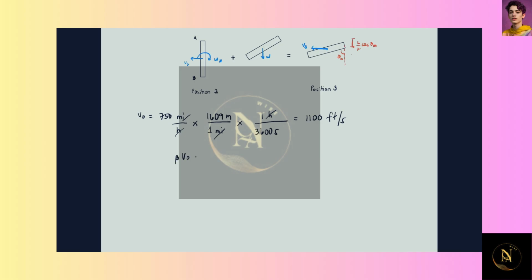Now, substituting the values in the equation for beta V0. So beta V0 equals the square root of the value of g in feet per second, 32.2, times 4, then 1 minus cosine 90 degrees, then over 3. So this is equal to 6.5524 feet per second.